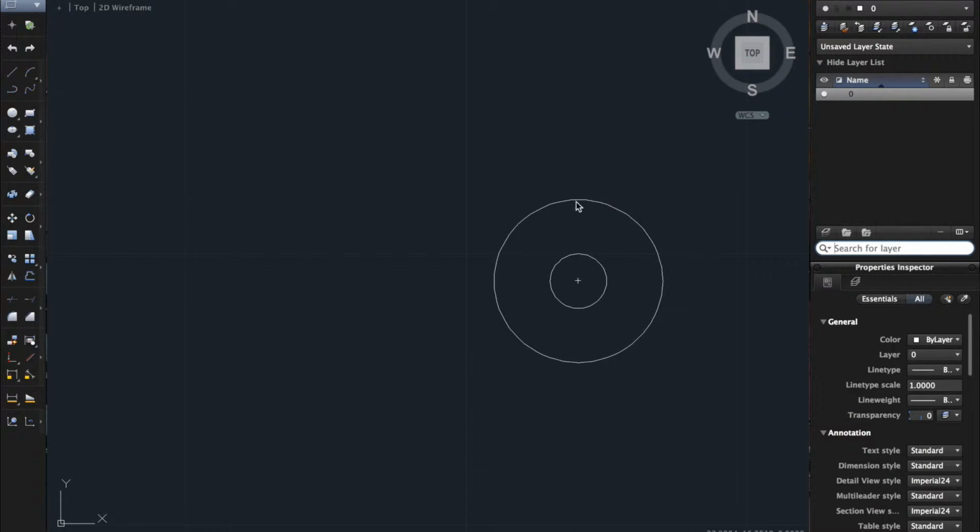We are going to do that. First I'm going to click on this line, turn on snap grid, click here. I'm just going to draw a line straight through. I'll show you guys why in a sec. Alright, so here you see I have this circle. What we're going to do is use a command that's trim.